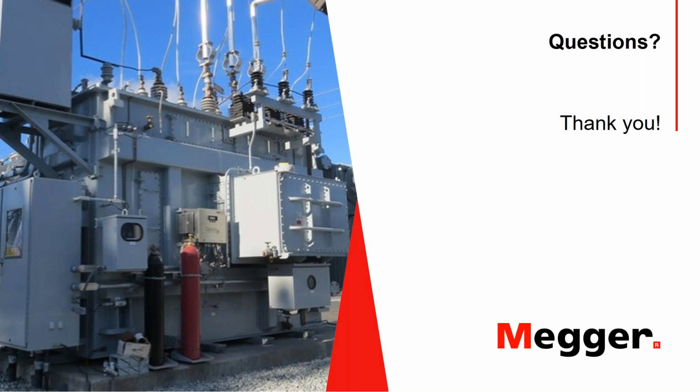Thank you. Next question is going to be for Daniel. Is there any specific method to use when testing a transformer with an OLTC? Okay, great question. I wouldn't say a specific method, but the recommendation is to use the automation that is offered with both instruments and the combination of the instrument and PowerDB. Dinesh mentioned a little bit of that. So when you have a set of windings with an OLTC, the OLTC is designed to change position when the transformer is energized.